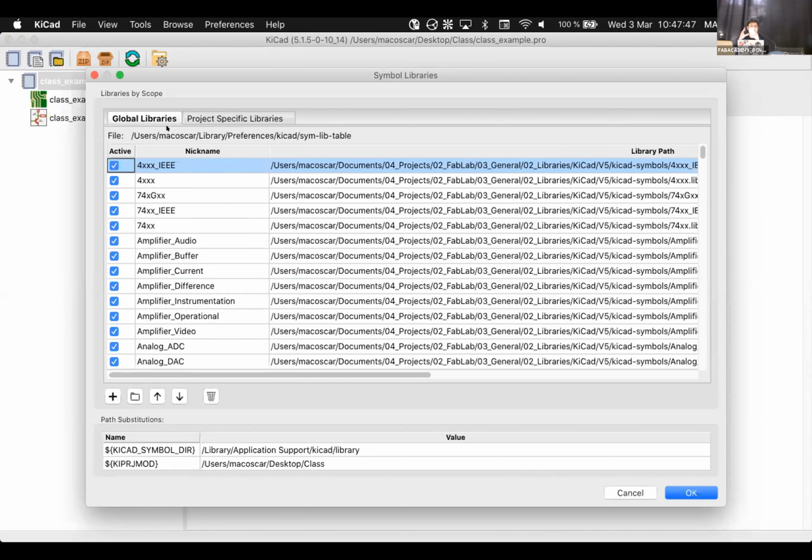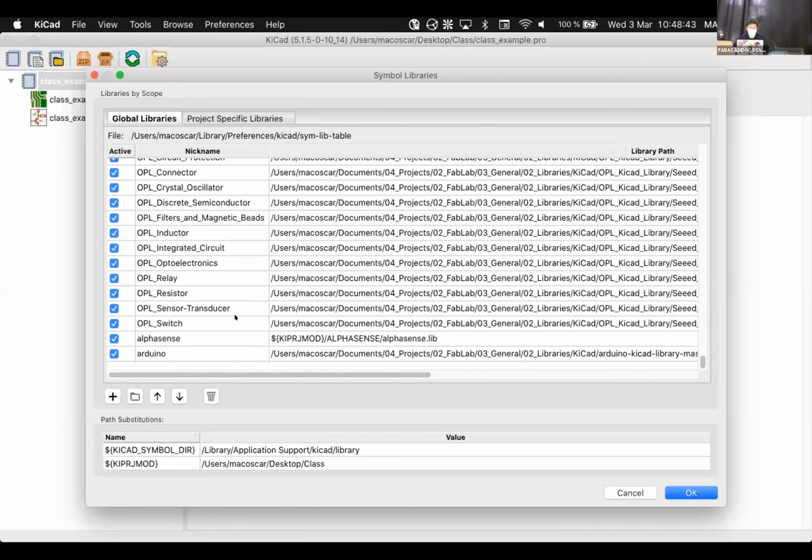So now, here you see that, for instance, I have one called Fab. This is the Fab library from the same one that we have just downloaded. I'm going to add the same one, I'm just going to change the name and we'll see how this looks, okay? So in order to add them, you probably have different icons. Giuseppe, please check this process because I know that different icons and different versions of KiCad change how these look. But basically you have to look for something that says add existing library to table, which in my case looks like a little folder.